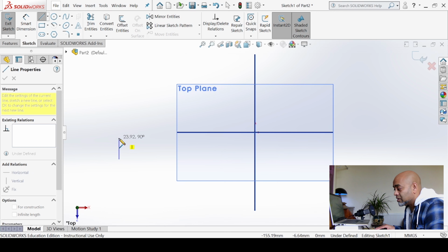So this yellow indicator here, it is telling us that we are about to draw a vertical line. That's what that means. It's basically a constraint, an indicator to say that you're about to commit to a vertical line there. I can move my cursor this way and it will draw a horizontal line for me, and probably around here somewhere it will show me that I am at 45 degrees or 135 degrees. All of that makes kind of sense.